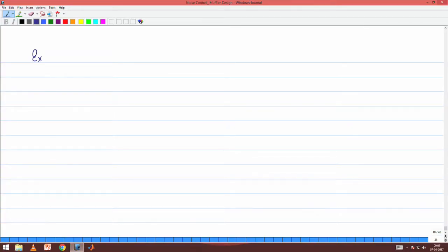We will see today some other muffler configurations which exploit that idea of creating a bypass line and thereby increasing the velocity ratio and the insertion loss. So, towards that end we will look at extended inlet outlet resonators.